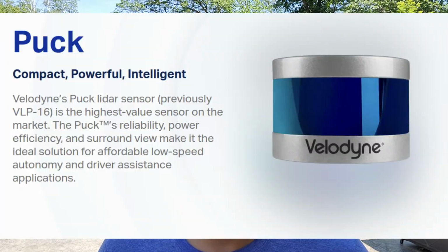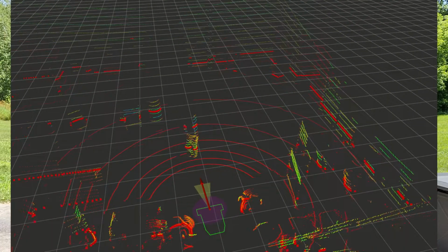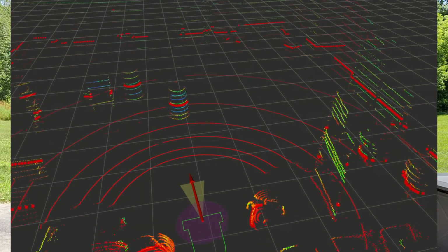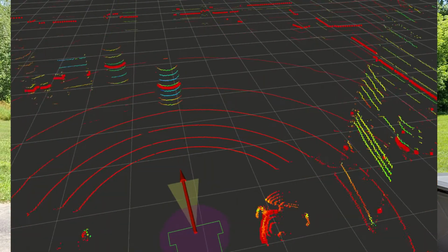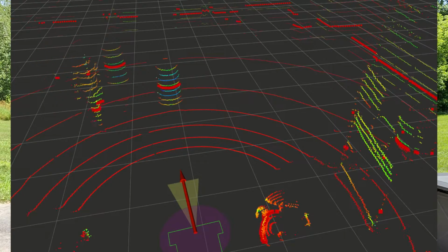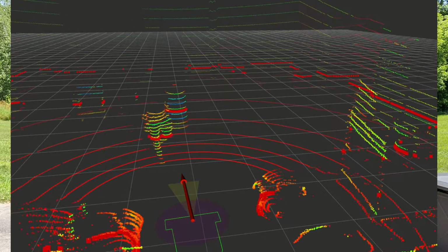I did a similar thing with the Velodyne VLP-16 Puck, which is a 360-degree 3D LiDAR. It's a very cool thing, but it runs 24/7. We might take our robot out of the lab for operations once or twice a week, but we leave it online all the time so we can run various experiments and do development. And these are things that are going to make your hardware last longer and really help your development process because you don't need somebody physically at the robot to start and stop these sensors.